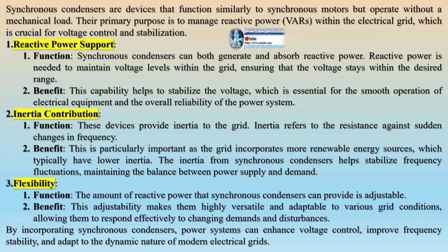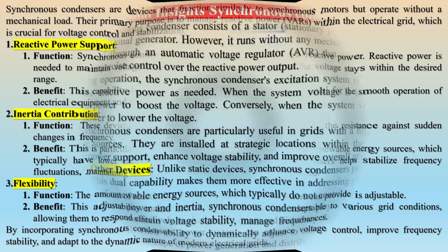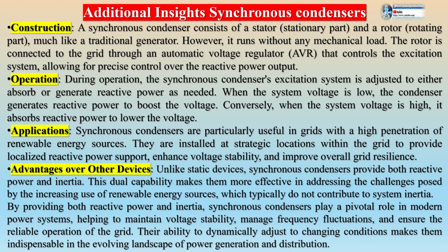Let us discuss synchronous condensers, which are essentially synchronous motors that run without mechanical load. They provide reactive power (VARs) to the grid, which helps in voltage control and stabilization. Here are some key points. Reactive power support: they can generate or absorb reactive power as needed, helping to maintain voltage levels within the desired range. Inertia contribution: they provide inertia to the grid, which helps in stabilizing frequency fluctuations, especially with the increasing penetration of renewable energy sources. The amount of reactive power they provide can be continuously adjusted, making them versatile for various grid conditions.